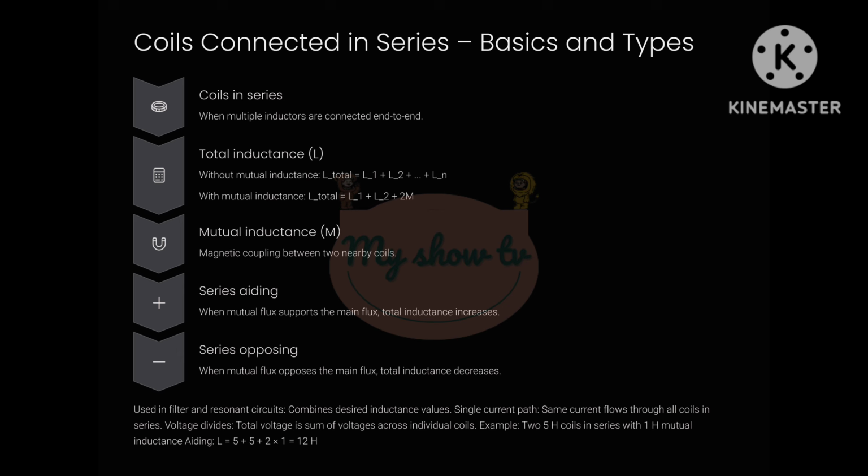L_total equals L1 plus L2 plus L3. If there is mutual inductance, coils are close and influence each other magnetically, the formula becomes: for series aiding, L_total equals L1 plus L2 plus 2M. Mutual flux helps the total flux. For series opposing, L_total equals L1 plus L2 minus 2M. Mutual flux opposes the total flux.